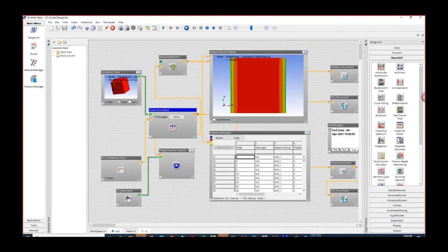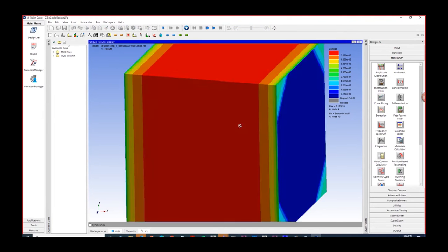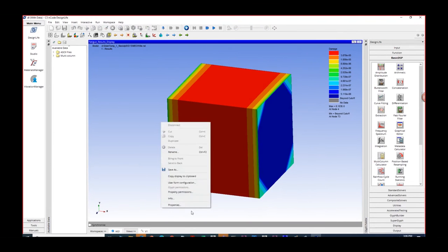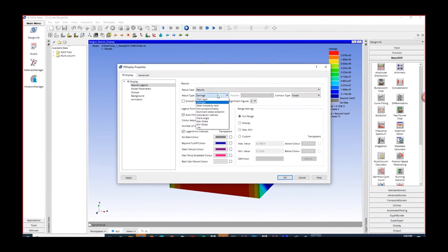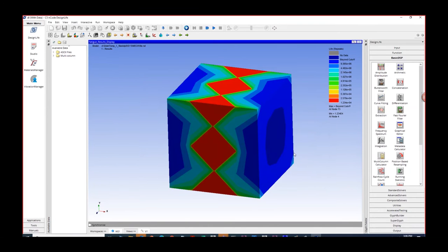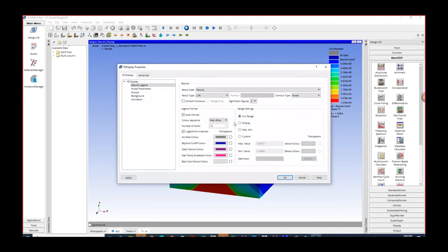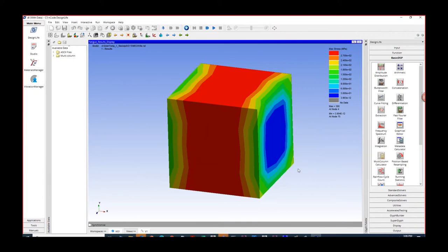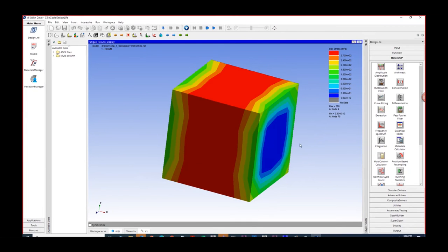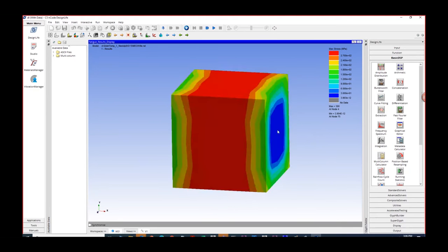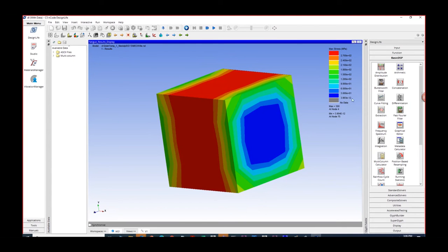And it is going to give the result. This is the result item. We can go here and plot life. So in this case, it is going to show some stress value. You can also plot the max stress, minimum stress, and so on. If you look at the max stress, it is showing 300. But if you look somewhere interior, it is showing 0 stress.